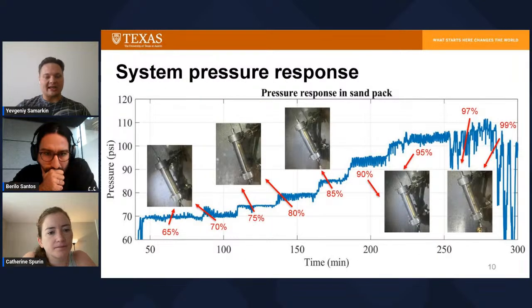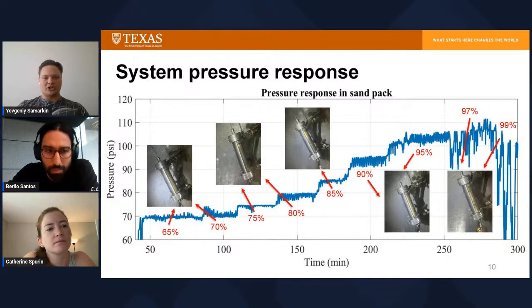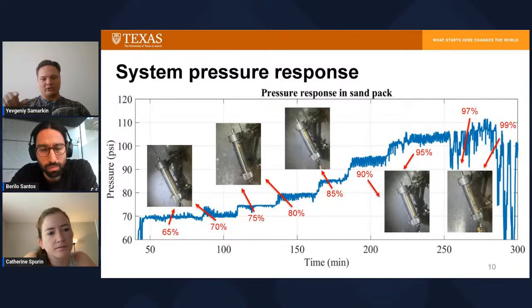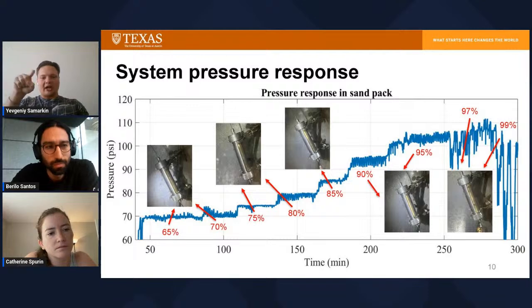Thank you very much. That's an excellent question. From this profile, you can see that once we increase the foam quality, which means we introduce more gas, then those fluctuations become more aggressive. So I wouldn't say we actually quantified those fluctuations, but in general, we would record that pressure drop over time, and then take the average pressure.